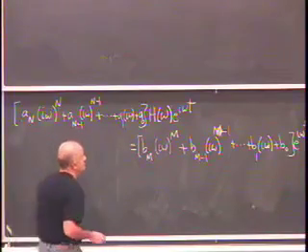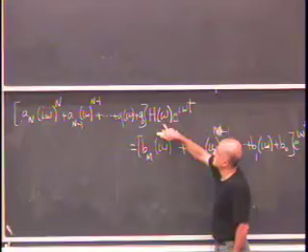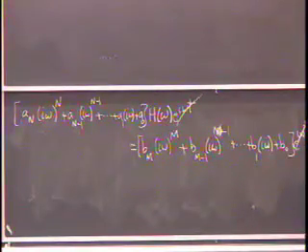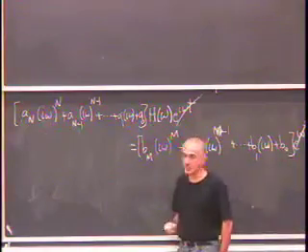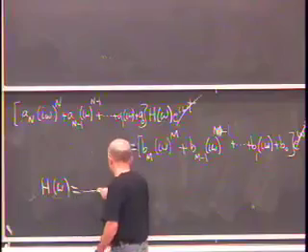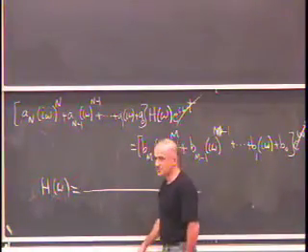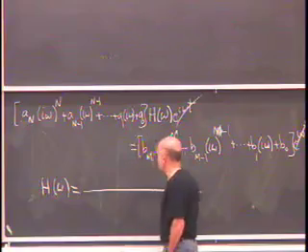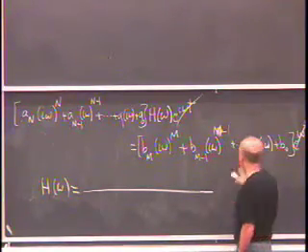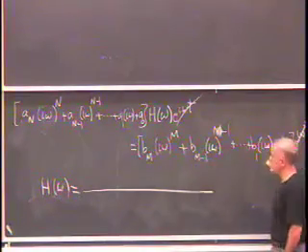And then, what's the next step? We're going to try to solve for H omega. So first of all, we're going to cross out H omega on both sides. These two go away. And then we solve for H omega. So that's a ratio. That's good. We want a rational function. And what's in the numerator? The numerator is b to the m I omega m, that whole thing. It's this whole bracket. Goes in the numerator.